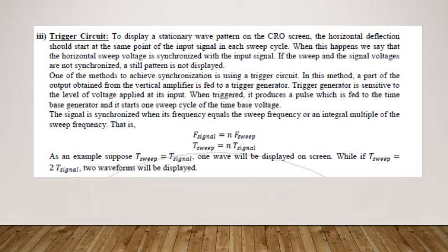One very interesting knob is also there with the CRO, that is known as the trigger circuit. Now, you are applying one signal on the y-axis, and to feed the x-axis you are applying another signal. Now the thing is, who will synchronize these two? There is a possibility that x will be first and y second, or y first and x second. You have to synchronize these two. Since you are applying two things from different sources, synchronization is important, and this synchronization is called trigger.